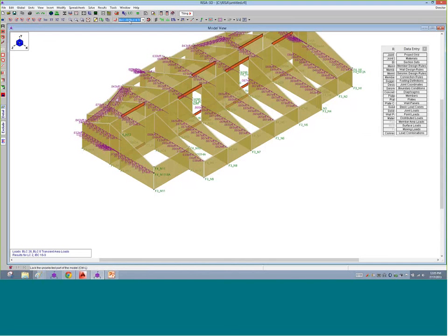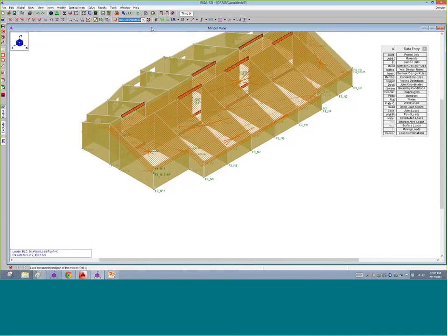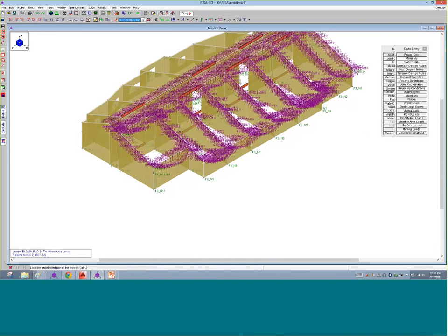But I also get the roof level load, so I'm going to get that uplift. What happened here is that an automatic roof load got applied, as you can see here, as an area load, and that's applied to this structure as an uplift on this side. And that converted right into a distributed load along the edge, or the perimeter, of that wall, or that envelope of the upper structure. So that loading got distributed there.